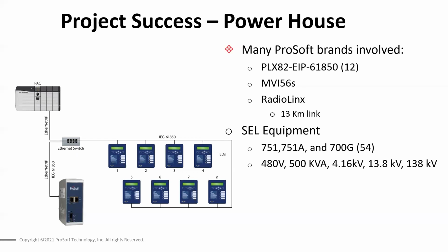Do the two RJ45 jacks on the new module allow for building a ring network, not just parallel redundancy to the downstream IEDs? PRP is the redundancy that most of the protective relays support. With 61850, they recommend having managed switches on the network just to help control some of the traffic. So we didn't implement a two-port ring on the module itself. It is a true PRP, so it's either going to be in PRP mode or simplex mode.